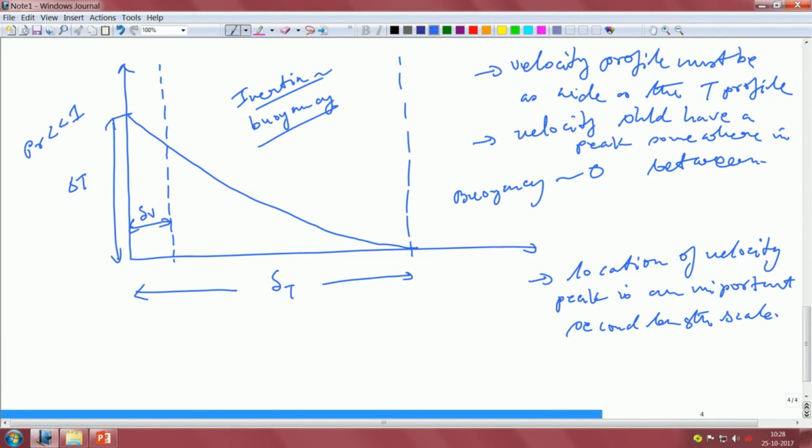Okay. Now, in this particular location, in that small band, what is important? The most important part over there is your friction can no longer be taken to be equal to 0, because it is a region very, very close to the wall where the shear is very, very important, right. So, there the friction cannot be neglected, right. What can be neglected though in that particular region is the inertia, right, okay, because it is a region very close to the wall, right.